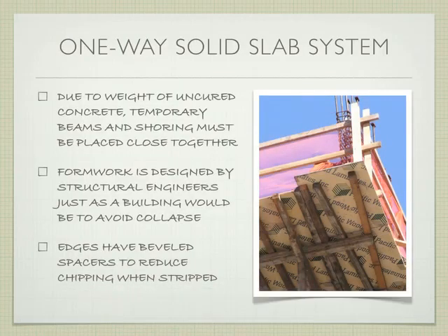And so due to that weight, the temporary stuff, the shores, the beams, the joists, all that stuff, tend to be really densely packed. Once the concrete cures, it can span the distance by itself. But when concrete's in its uncured state, it's very heavy and doesn't have any structural support whatsoever. So we need a lot of extra support so that it can cure in its proper place,